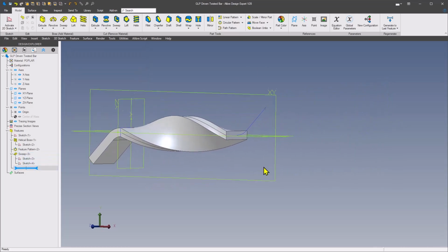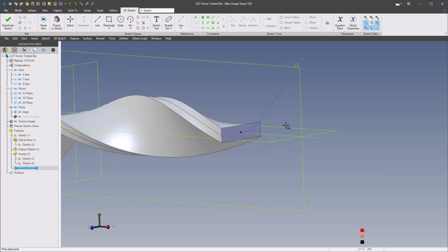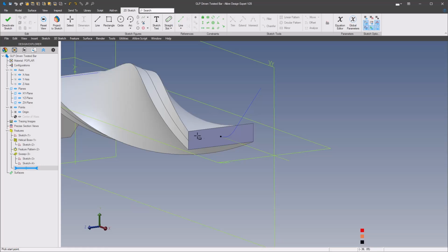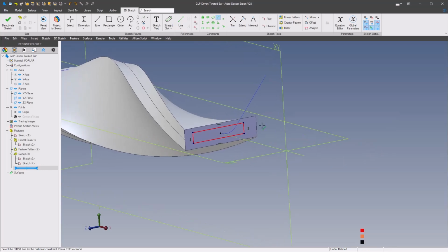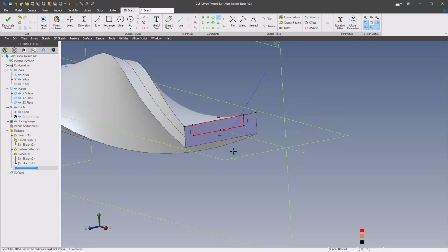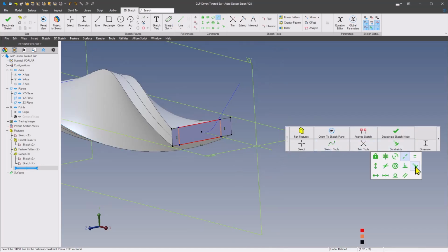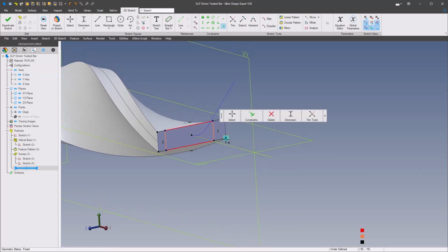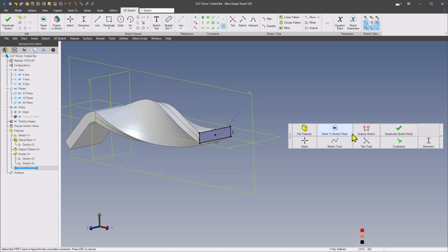we're done. Then we go to the opposite end, and we'll just repeat the same process, except what I'm going to do here is I have run into some problems where if I do a project to sketch here, when I'm changing material thickness, it'll sometimes lose the reference on this sketch, just using a project to sketch on this end face. So I'm going to use a sketch rectangle, and I'm going to put some collinear constraints on the long sides, and then on the ends I'm going to do coincident from the end nodes of the rectangle to the end node of the reference geometry, and that takes care of that.